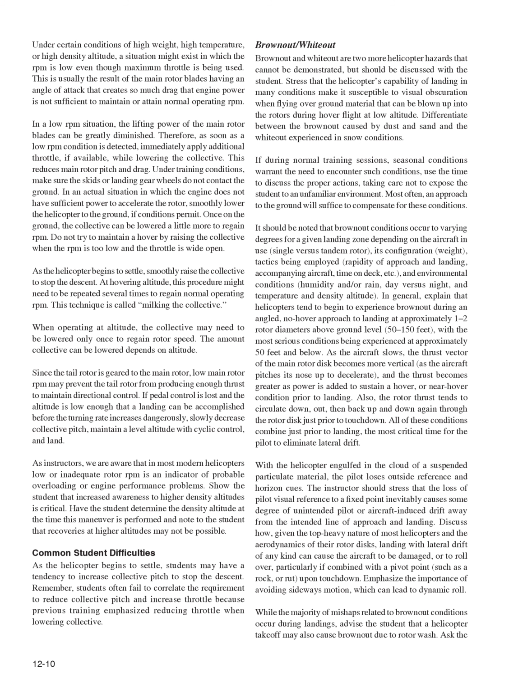Common student difficulties as the helicopter begins to settle. Students may have a tendency to increase collective pitch to stop the descent. Remember, students often fail to correlate the requirement to reduce collective pitch and increase throttle because previous training emphasized reducing throttle when lowering collective. Brownout/whiteout.